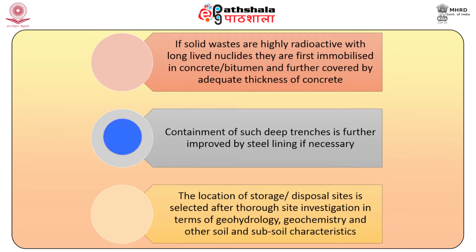Containment of such deep trenches is further improved by steel lining if necessary. The location of storage disposal sites is selected after thorough site investigation in terms of geohydrology, geochemistry, and other soil and subsoil characteristics.